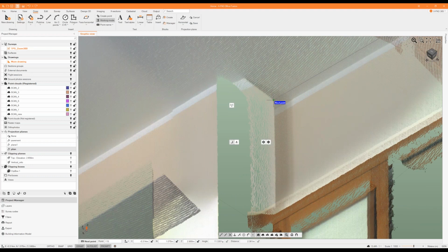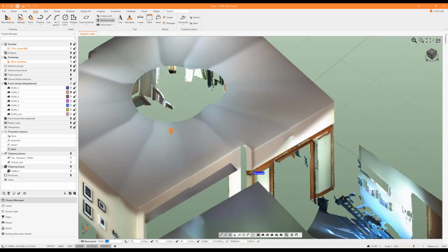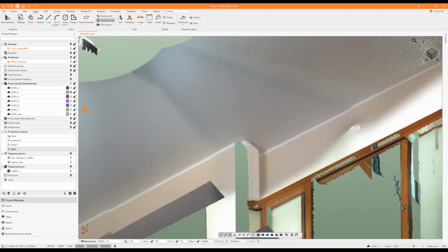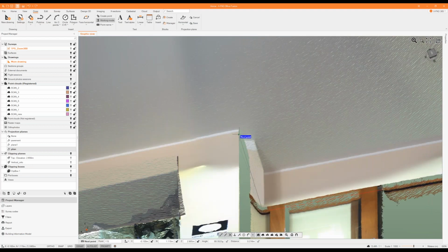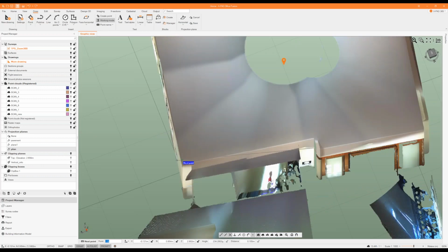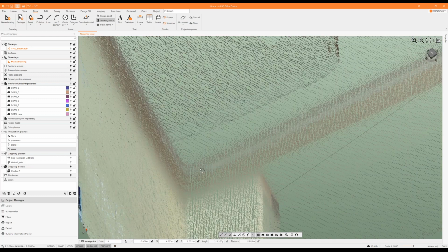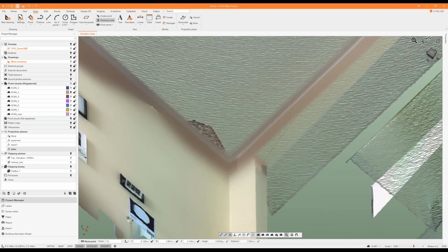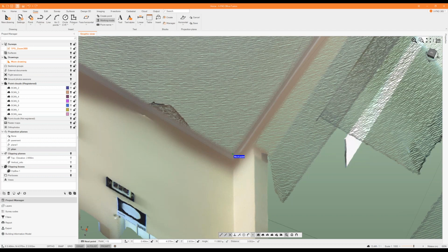Again, I can use the smart drawing functionality. And as you can see there, the polyline will be automatically projected to the 2D plane. So in that case, I can also deselect use Smart Magnifier and only select the points. Now I can reselect Smart Magnifier, just click in the position, and here we have also another option: sphere selection or section selection.